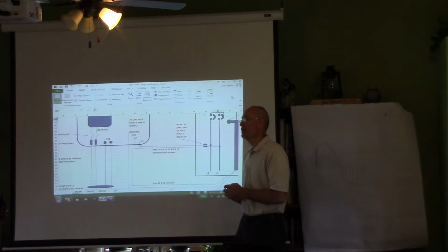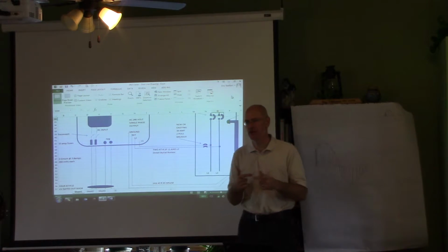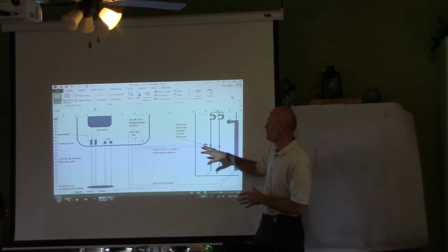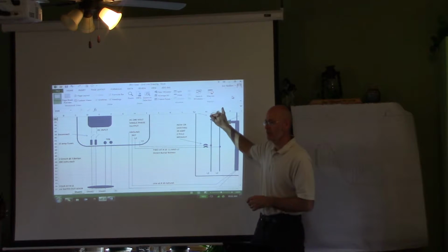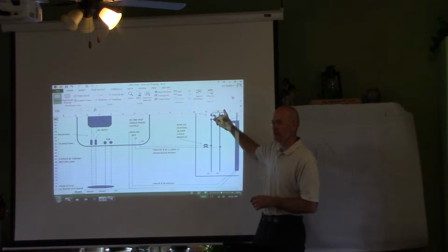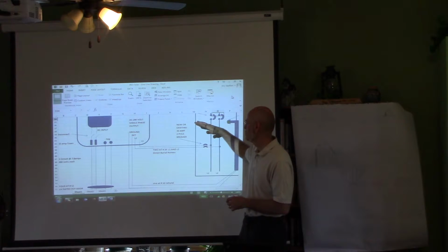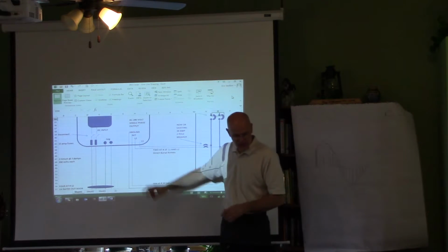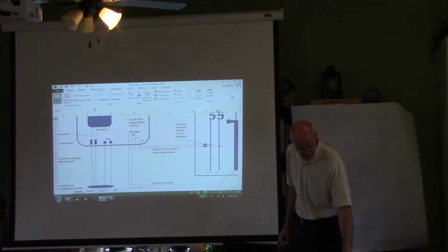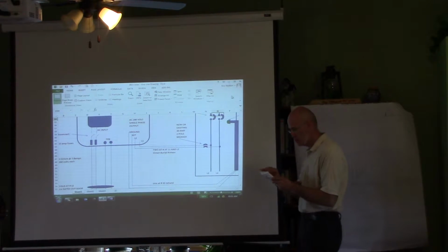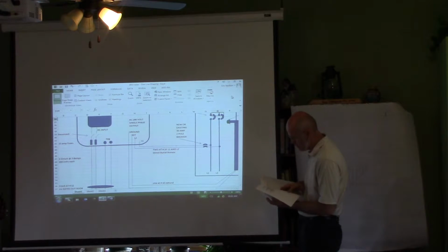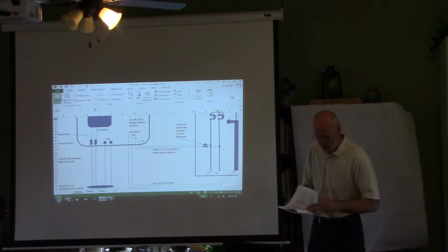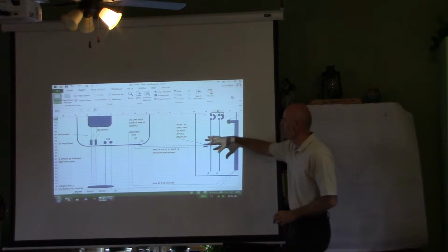But here's where we hit a safety issue. This is an on-grid system. This inverter needs a reference point. Its reference point is the utility. If the utility disappears, that means that voltage is dropping. It goes below the threshold of safety on this inverter, which I think is 208. 208 VAC under voltage, low level trip level, 208, yep. If that 220 volts drops to 208, the inverter shuts off.